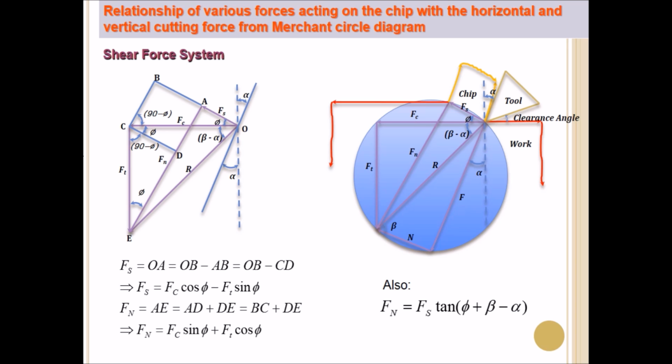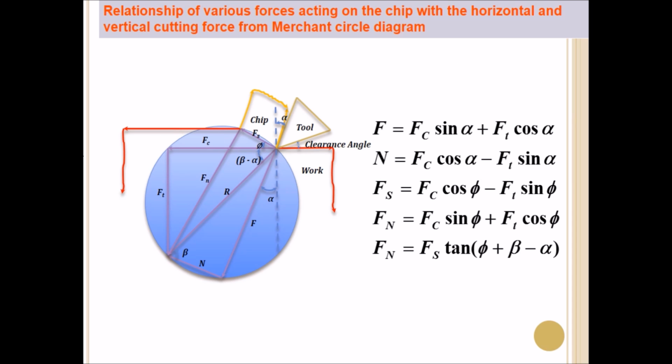Now we'll see the shear force system, where shear force is acting along the shear plane. And here also similarly we can express Fs and Fn, the shear force and the normal to shear force, in terms of Fc and Ft, which are the horizontal cutting force and vertical cutting force. And hence finally we can find out all the results for all the forces which are acting in the scenario.